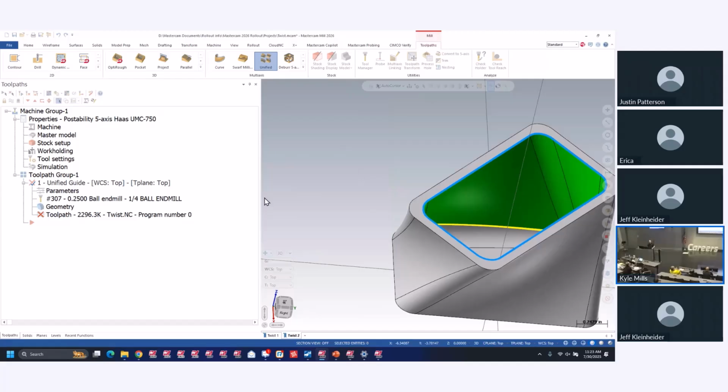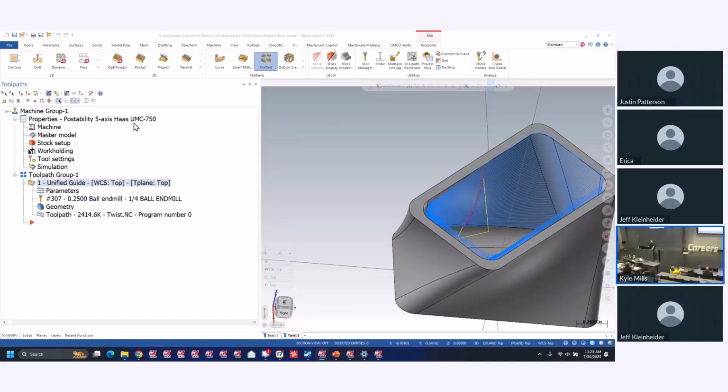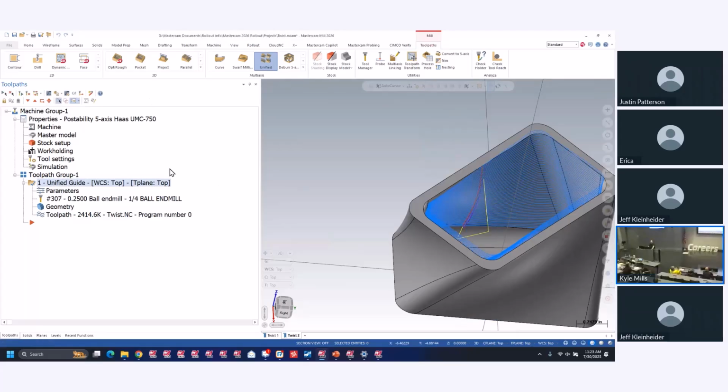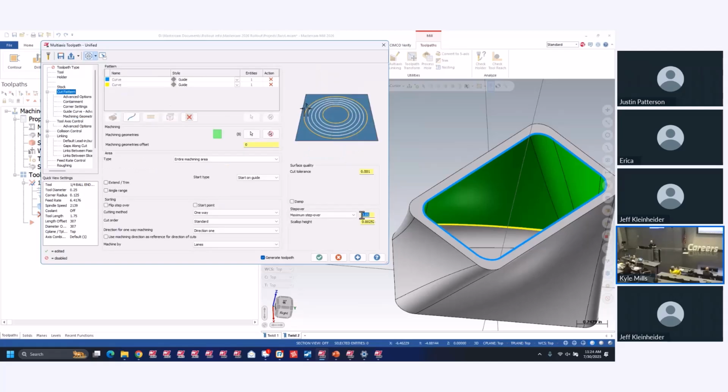Let it think for a little bit. I'll probably open up the step over on the next one to make it calculate a little bit faster. There we go. Oh, other 80 degrees. Good time to change that step over anyway. That's one thing I've noticed with Morph and Guide. They're opposite on which way you flip them. So sometimes you have to play with it a little bit there. So I'll open up that step down to 100.